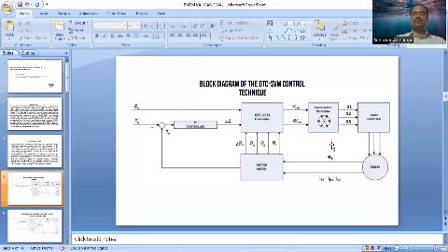If we observe this particular block diagram without extended Kalman filter, the proper selection of state voltage vectors S1, S2, S3 in the 360 degrees matters. Here there are 6 regions. If we don't select a proper state voltage vector S1, S2, S3, the output of the PWM inverter will not be specific and precise. Thereby, we cannot get the required amount of output voltage applied to the PMSM, which will result in torque ripples, flux ripples, and thereby affect the performance of the motor.